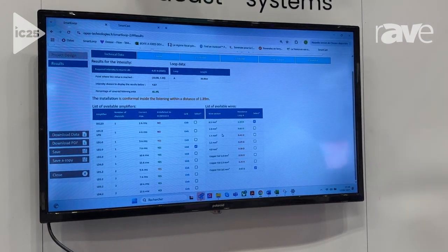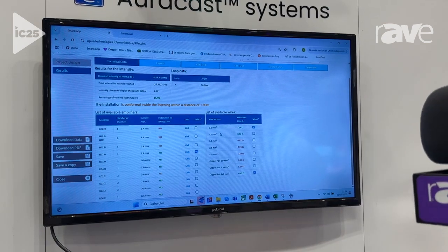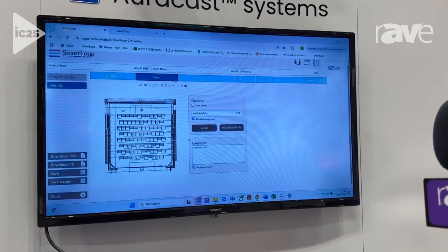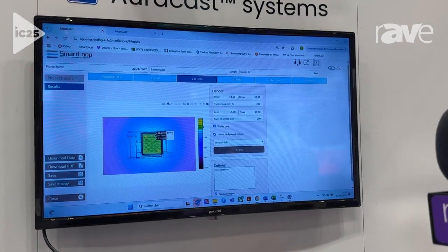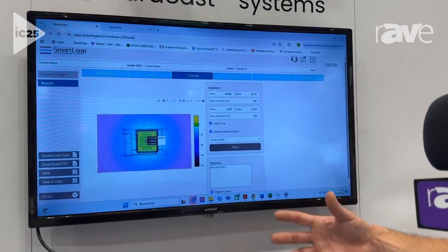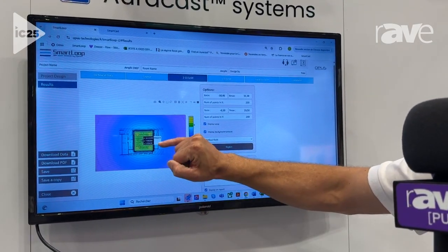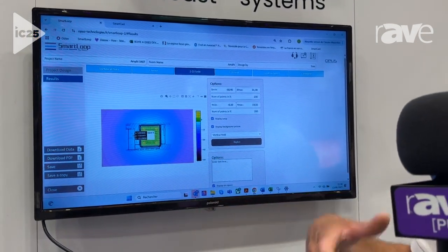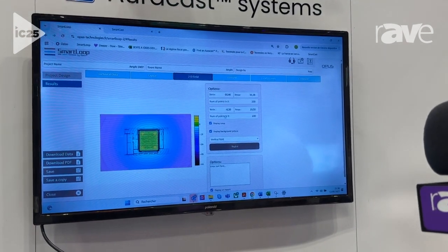The cable section you should use for this project, the length of cable you need, how you would install your cable within your room, a 2D simulation of the audio reception. So induction loop systems are covered by the IEC 60118-4 international norm. Here you can see the audio reception inside of the room, but also outside, to check if the confidentiality is respected outside of your room.